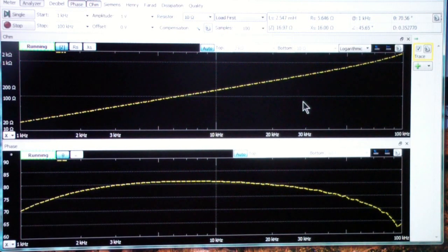But we would have to load the primary if we wanted to get rid of the effect of those parasitic resonances. And that is basically what happens in the output transformer of a tube circuit. Now, in a second, we'll move on and look at some things like that.